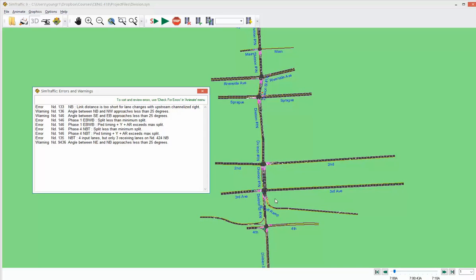If you're familiar with the Division corridor up in here, there's a lot of kind of strange weaving motions that come, you know, with these intersections. It also points out when it's not good design. So here it's less than 25 degrees. It's pretty unusual how we have a leg of the intersection essentially coming in parallel to the other. So these will still run, and it's just sort of pointing out, are you really sure that that's what your intersection looks like?